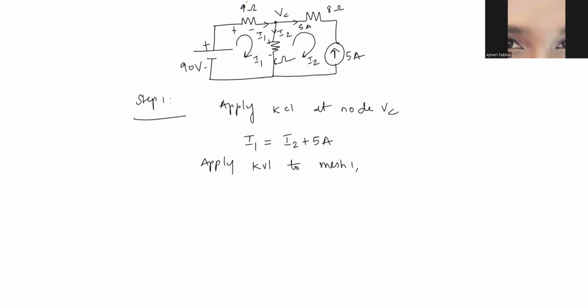Whenever you find resistance, just multiply it with current I1. So basically, you are writing V minus I into R is equal to 0. Whenever you have voltage, just write voltage as it is. Whenever you find resistance, you have to multiply it with current, and there will always be a drop across the resistance. So that would give you minus 9 I1. Now, if you see here, plus 2 minus, again, it's a drop. And here, how much you have? You have 6 ohms given.